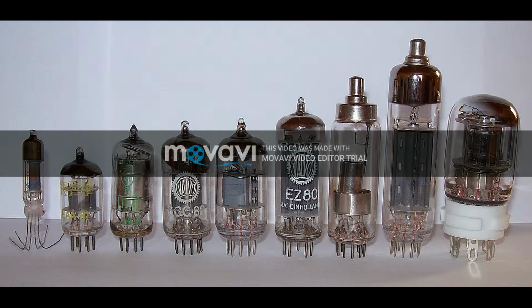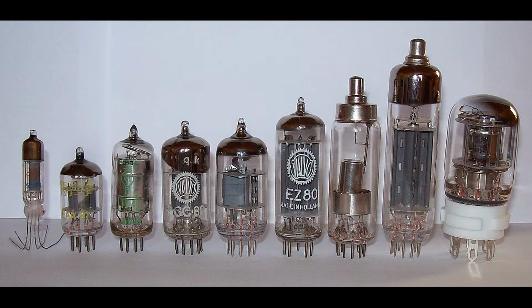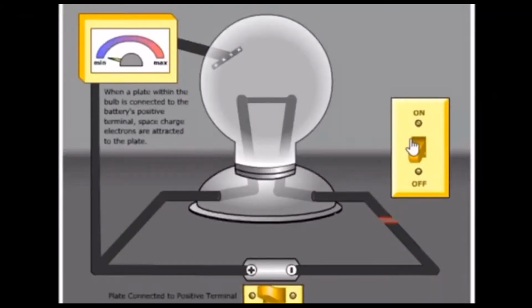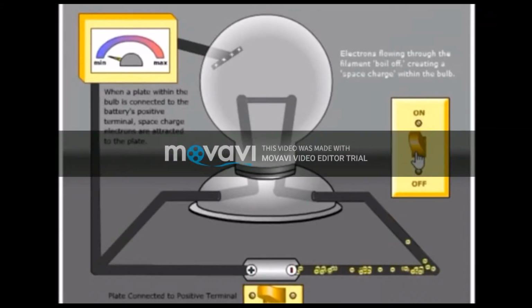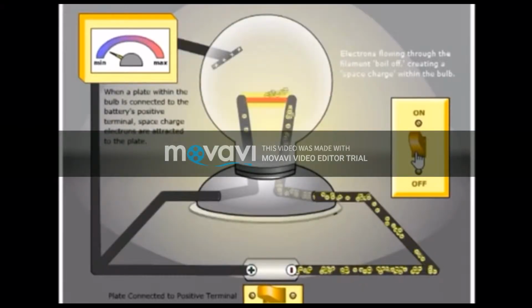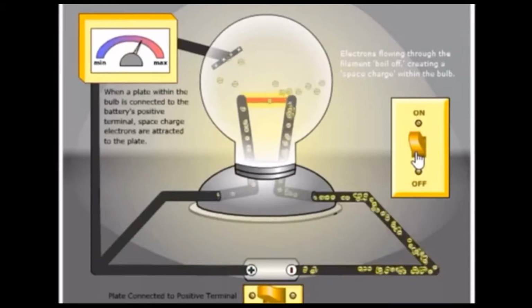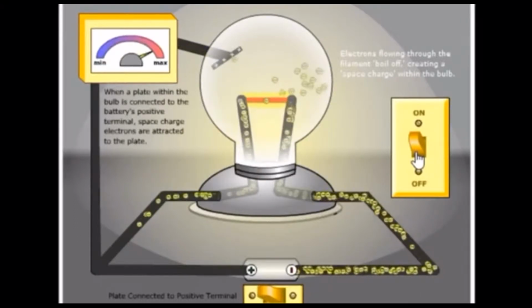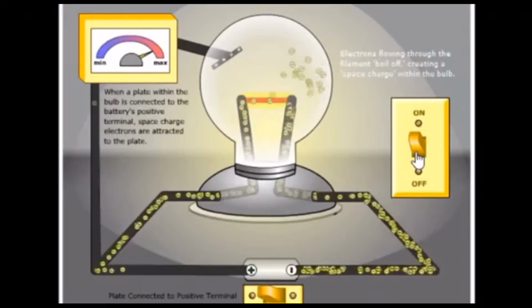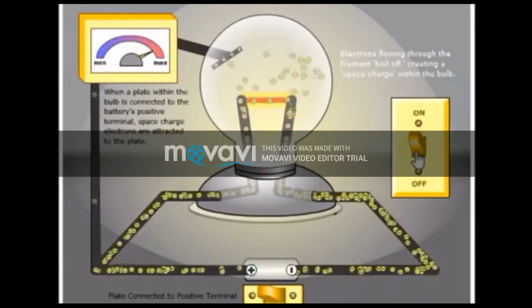Edison built lamp bulbs with a second element inside the envelope, either a wire or a plate, and showed that when this extra metal electrode was put at a negative potential relative to the filament, there was no current between the filament and the electrode, but this was reversed at a positive potential. Then a current flowed in the circuit if the filament was sufficiently hot. He also found that this current increased rapidly with increasing potential. This current going just one way was called the Edison effect and was established in a patent application for the first voltage regulating device.